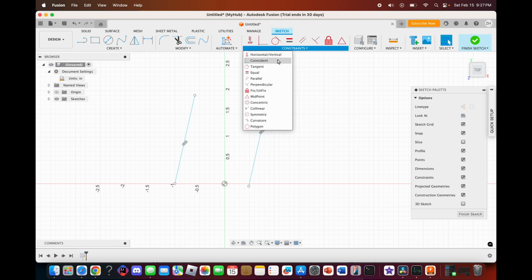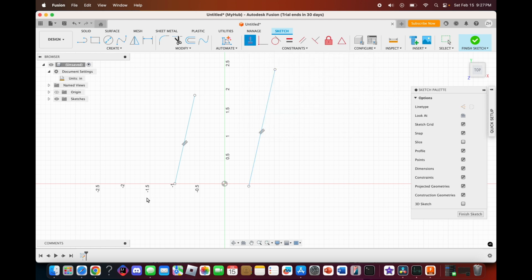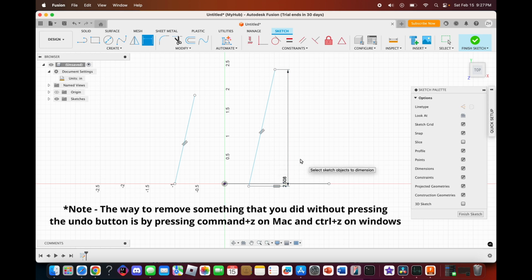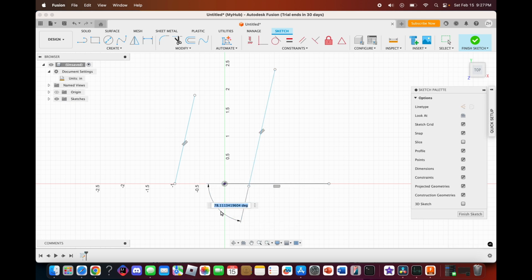So let's go to, where is it, horizontal. Instead of having it at an angle like this, we can actually see the angle right now. Hold on, let's draw a different line at the center like this. Now we can see that the angle is, oh my goodness, 78 degrees. That's not straight. Instead of modifying both of these to be 90 degrees, let's delete this line real quick. We can go to our horizontal, click these, and boom, they're instantly straight.